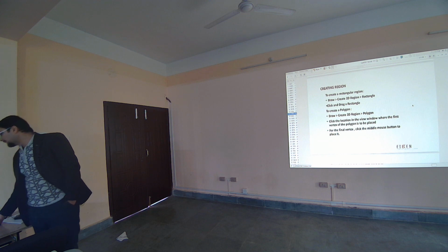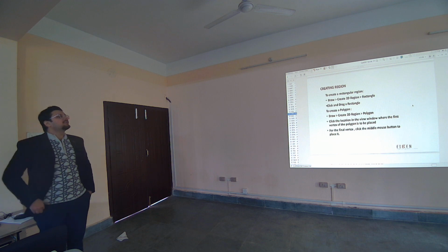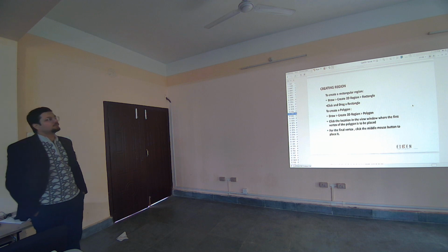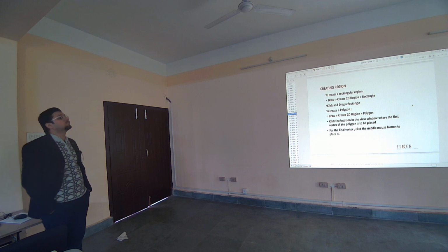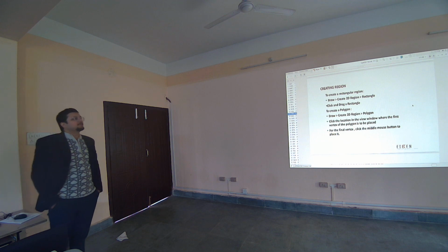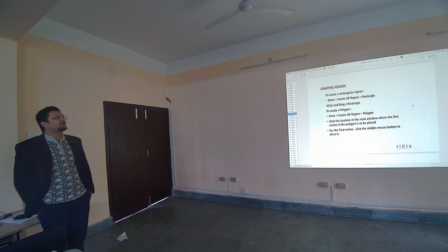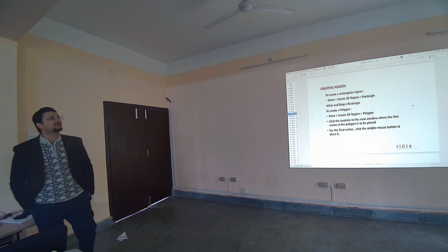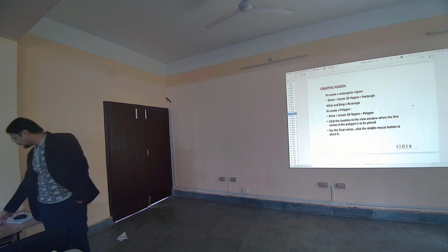These are the steps that we'll follow to create a geometry again. To create a region, we'll follow these steps. If you want to create a rectangular region, then we'll go to Draw, then to 2D Region. Since I have selected this 2D region, that means I am working in 2D mode, right? That's why it is a rectangle, otherwise it would be a cuboid. So we'll go to Draw, then create 2D region, and there we'll select a rectangle. Then click and drag a rectangle to create a polygon. That's it.